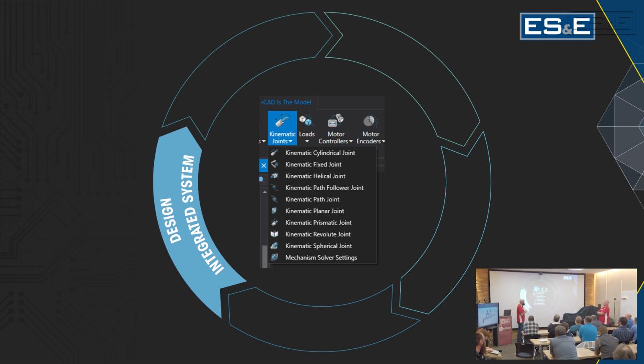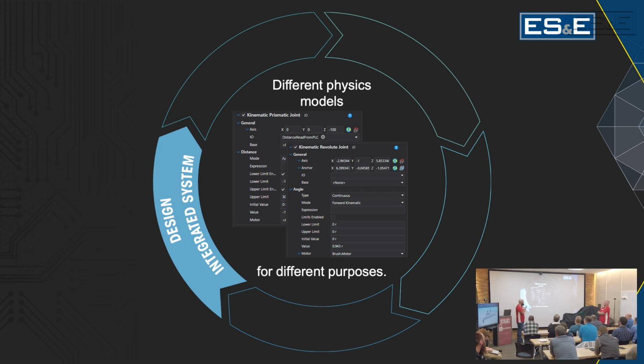You just mark it up, standard like you do with other models. You define the way that the physics is going to interact with the machine. You might have a linear movement. In this case, we've got our slide axis, so that would be your prismatic joint. You're going to have a linear type movement, and then we also have a rotating brush, so that's a revolute joint. Just different physics for different purposes, basically.